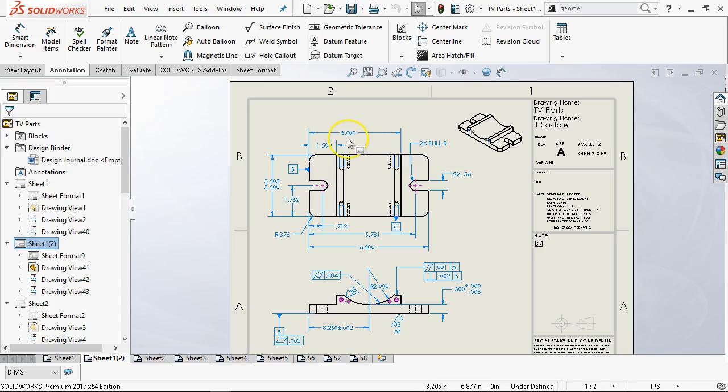So when I see a 2 decimal place dimension or a 1 decimal place dimension, I'm still carrying it out 3 decimal places. It just works better to stay in that mindset, stay in that consistency. So understanding on the design side, I don't necessarily need 3 decimal places, but understand what happens when you put 2 or 1 or none. And definitely understand what happens when you put 4 or 5 when you don't need it.